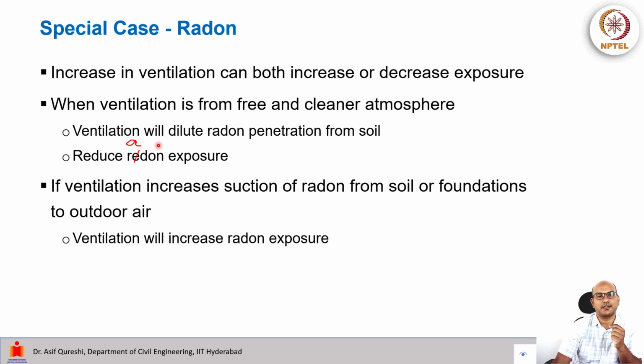So ventilation will dilute the radon penetration from soil and reduce the radon exposure, because the outside is free. If the ventilation increases the suction of radon from soil or foundations to outdoor air and then outdoor to indoor, ventilation will actually end up increasing the radon exposure.